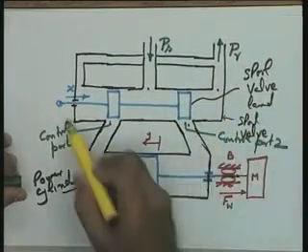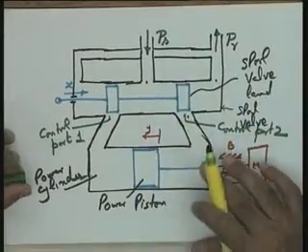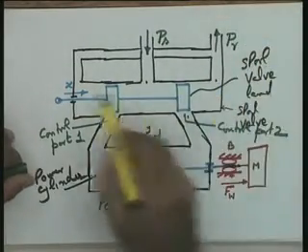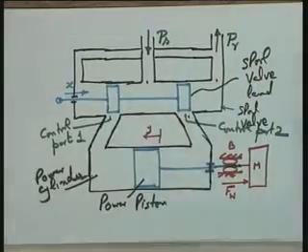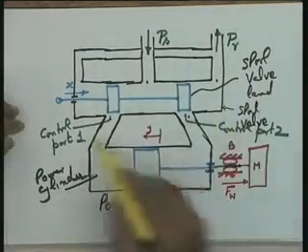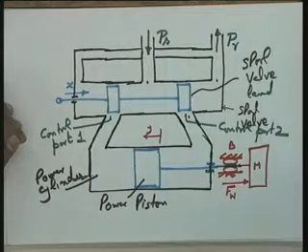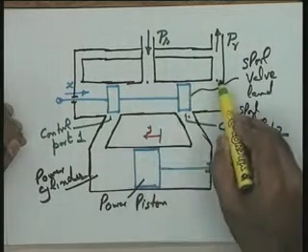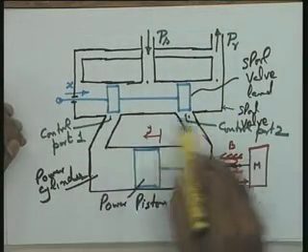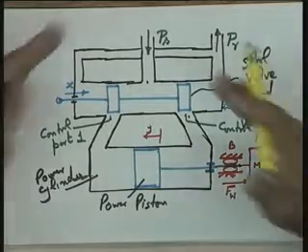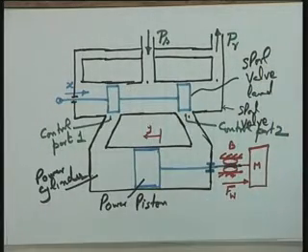Therefore the spool valve under consideration is a 4-port device, because the two drain ports have been linked by a suitable pipe, and hence the total number of ports in the spool valve is 4. One the supply, this the reservoir, and two control ports. I hope as far as the device is concerned, this should be more or less clear, and we can now see the working of this particular device.